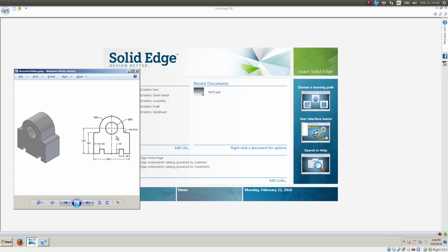We have here a sketch profile that we want to duplicate using Solid Edge. And this could be extruded to form a base feature like is shown here. We're just going to make the 2D sketch. The way it'll proceed is create a new part and then just draw the rough outline of this shape. Finally, I'll add lots of constraints and dimensions, which are themselves constraints, in order to lock it into the shape that we want here.